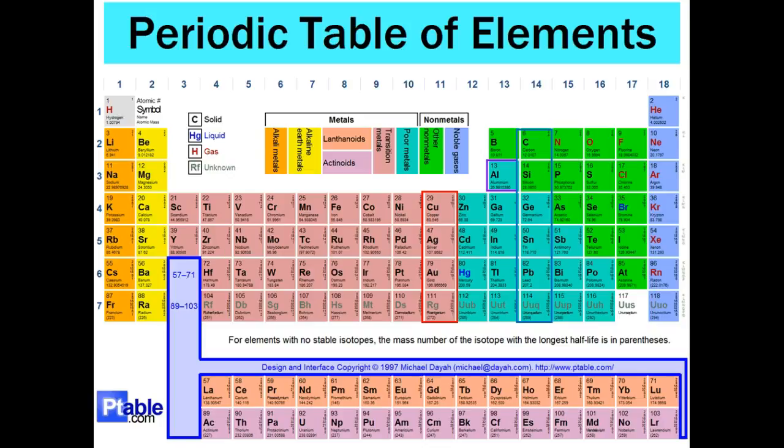The problem with carbon, though, is we used it as a semiconductor. Carbon resistors were the first resistors. The problem is that carbon varies its resistance a lot with temperature, so we don't see much pure carbon resistors anymore. But the original resistors were carbon. All they did was compress it down to the resistance they wanted. They put 2 leads in, compressed it down, coated it with some paint and put some colors on there.